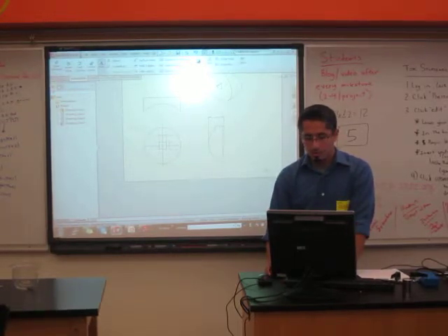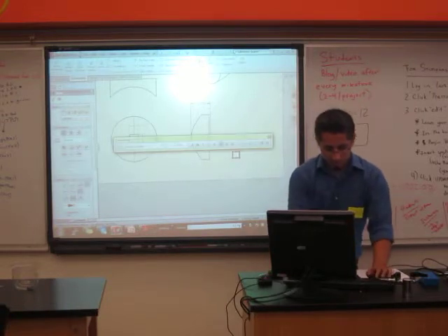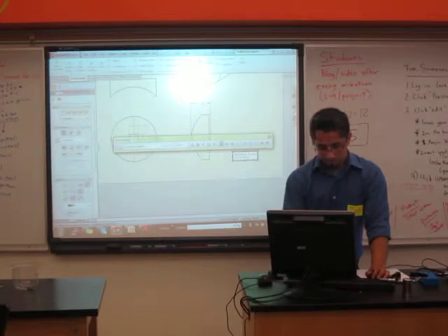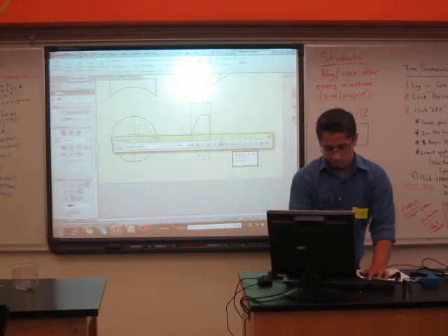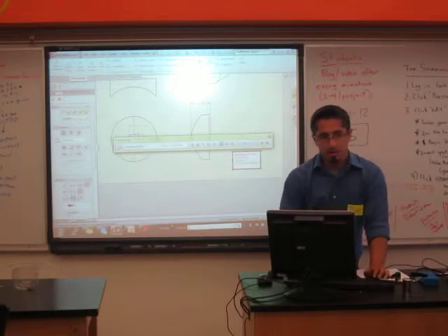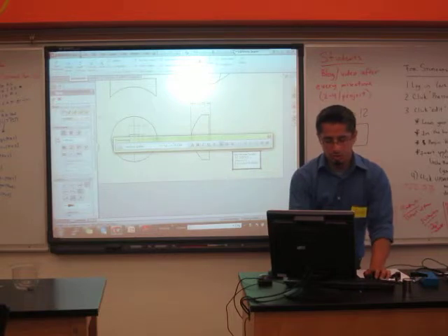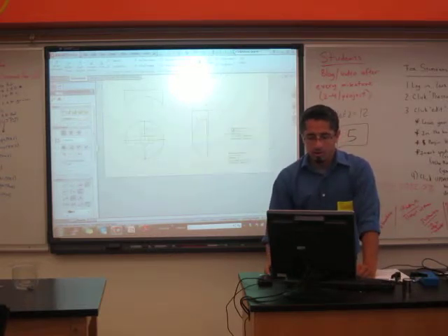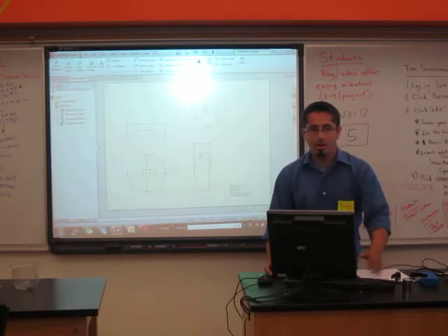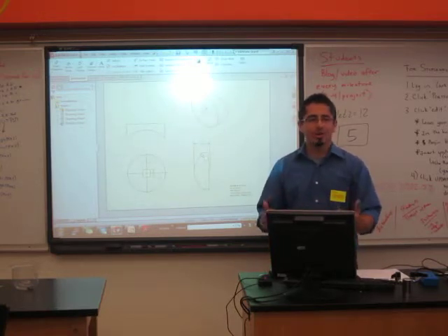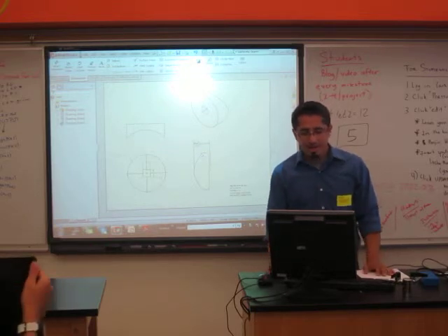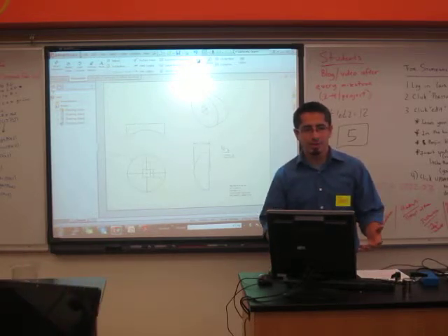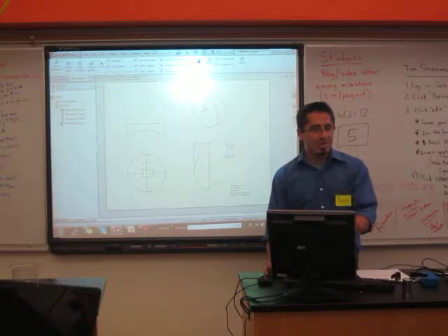In terms of the notes you want, something simple. Name, date, version 1, rounded washer, and then if you want to get fancy, because these are good drawings, material, steel, 304. Okay, simple. And then you're done. Go and print that out, make a PDF, put that in. Now if I want to build this thing, I have enough information. CAD is kind of dry, it's not super exciting, we're not making V8 engines, but this is enough of what you need to get started to make your thing.